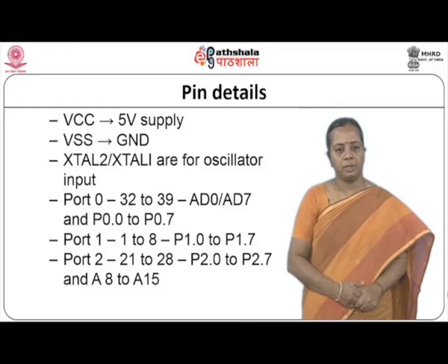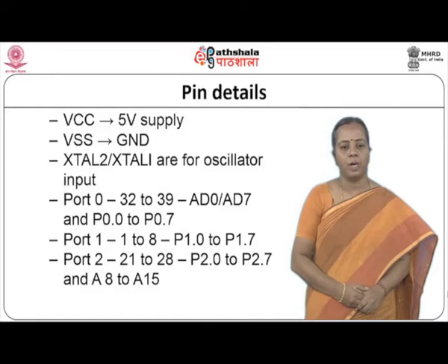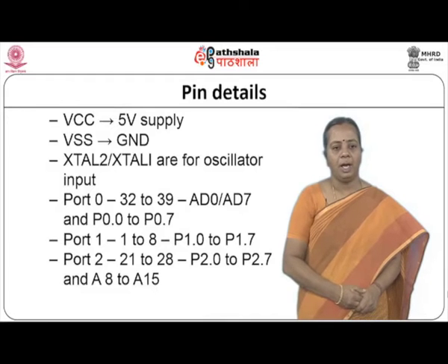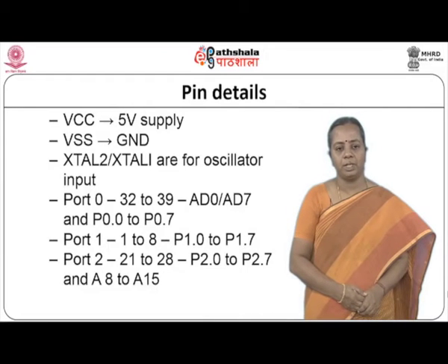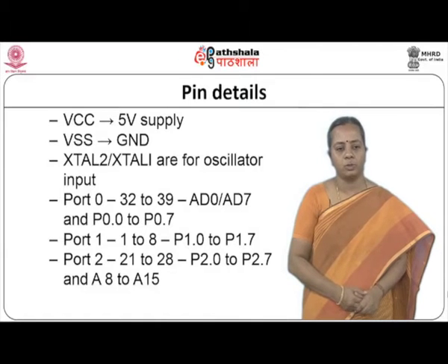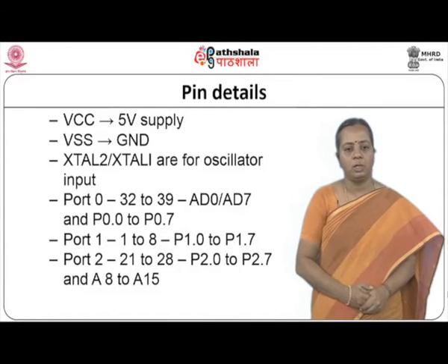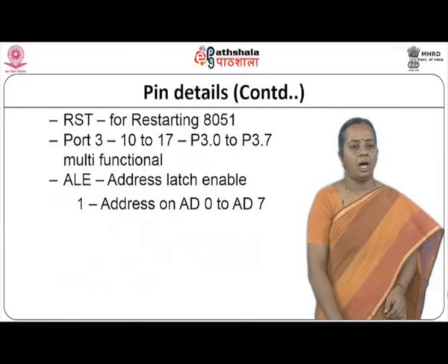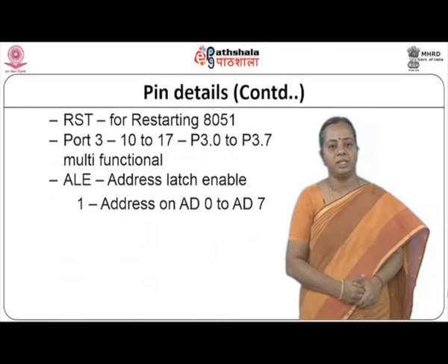Port 1 is on pins 1 to 8, and port 2 is on pins 21 to 28; port 2 is also used for sending address to memory. The RST pin is for restarting your 8051.